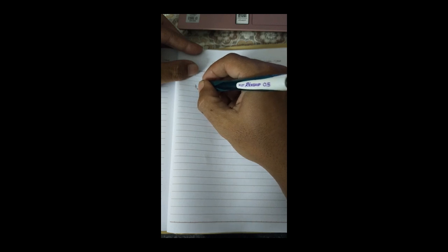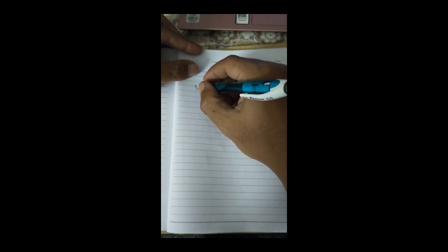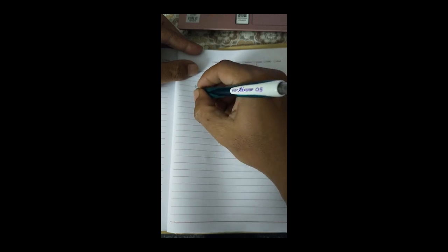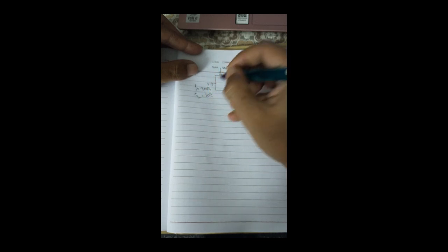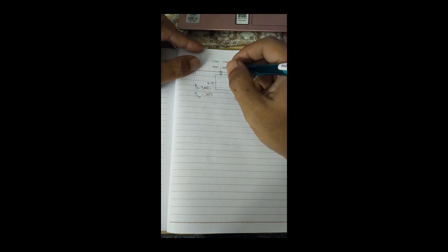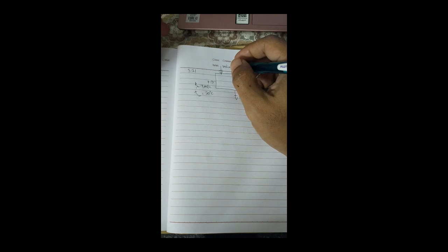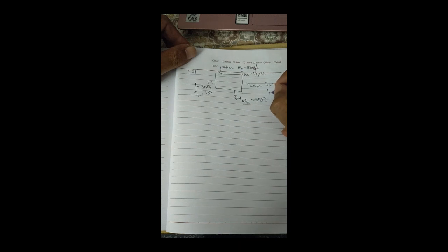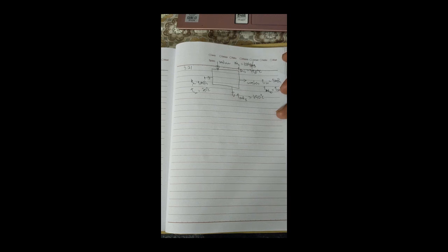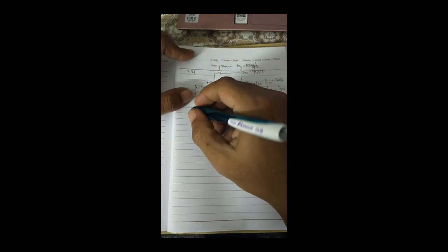So P water, P1, is 5 MPa, T1 water is 20 degrees C. Okay, so the question has given directly to neglect the pressure drop, which means that P2 water is 5 MPa, and T2, the T out of water, is T sat, as given directly, it is not completely vaporized, so T sat. Okay, alright. General equation.